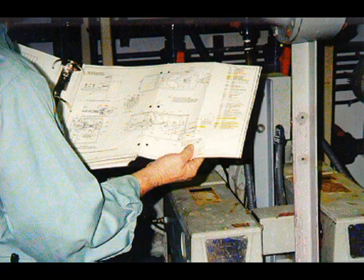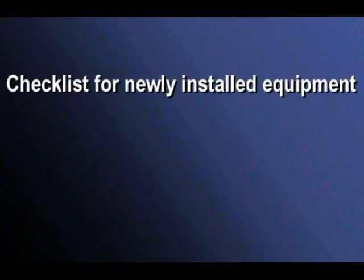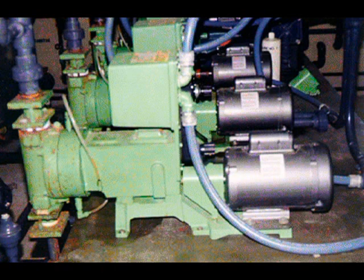As with other equipment in your plant, refer to your manufacturer's literature for specific operation and maintenance instructions for each chemical metering pump. Here are some. The supplier's literature should indicate how new equipment should be installed. To ensure that the equipment is properly set up and operating, here are things to check when examining newly installed equipment. 1. Is the pump mounted in the proper upright position?